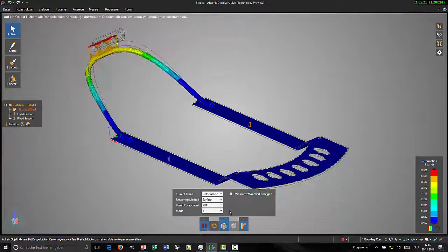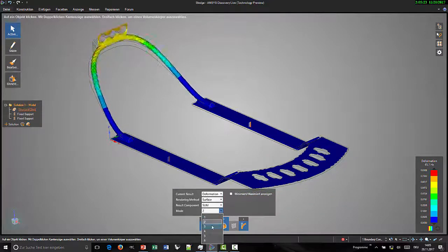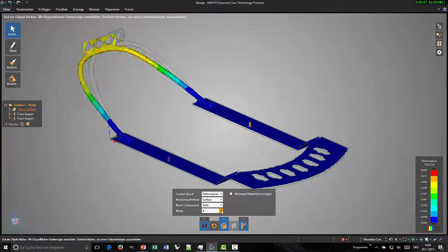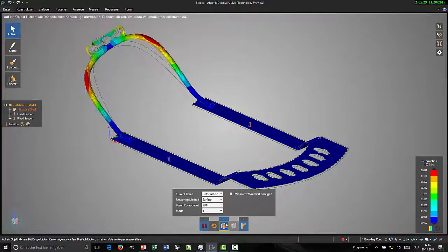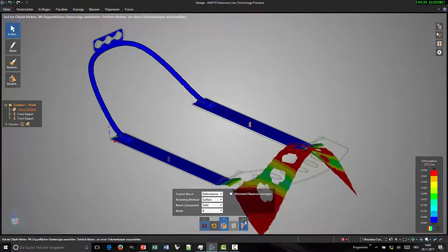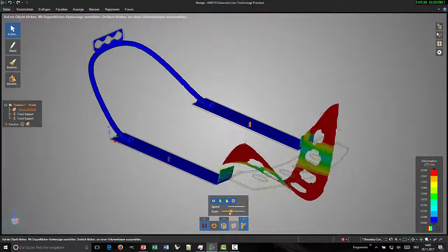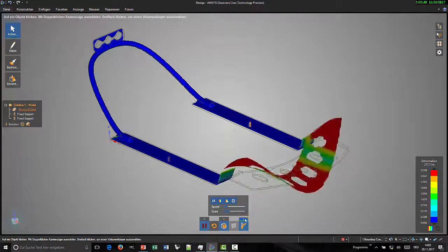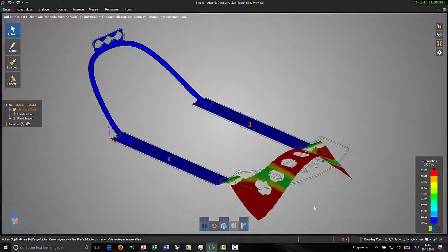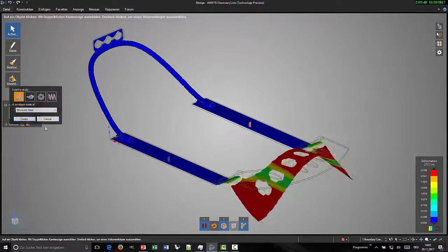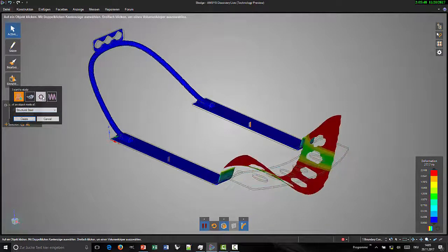So you see the different modes here, either on the upper bar or the things behind, this construction behind there, because those are not so stiff anymore. And like this, you can investigate a bit your structure. I personally like really a lot to do modal analysis before doing any other kind of observations, to get an idea about the stiffness of the structure and so on and so forth. So you could, for example, discuss about stiffness.